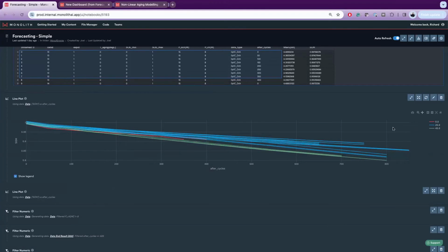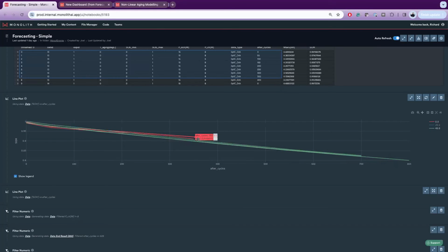For this particular battery, we've run the aging tests at 0 degrees, 25 degrees, and 45 degrees. And I've seen this before. Sometimes in your engineering requirements, you start off saying, you know what, we don't need 0 degrees. We're controlling our battery to constantly be at 25 degrees, so this is not necessary. But then you later figure out, oh hang on, we actually need to go to such low temperatures after all, so let's add 0 degrees to the test matrix. And so you end up with your 0 degrees matrix being only half as progressed as the rest.